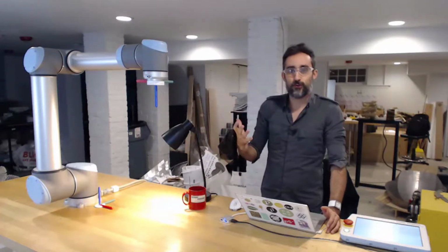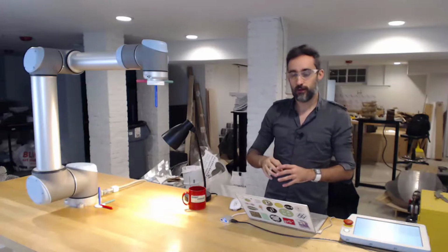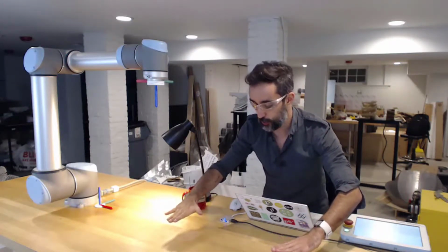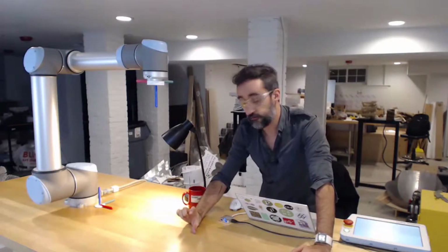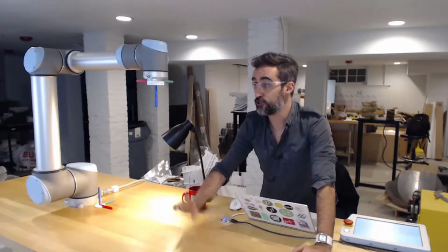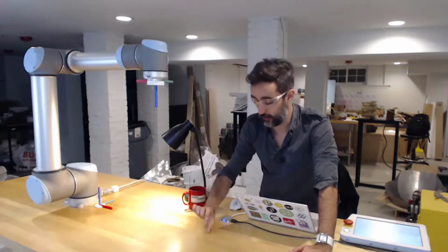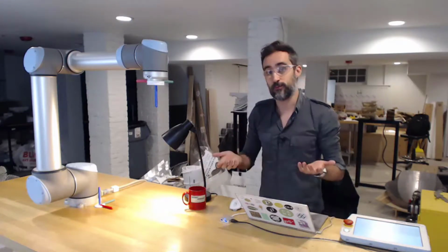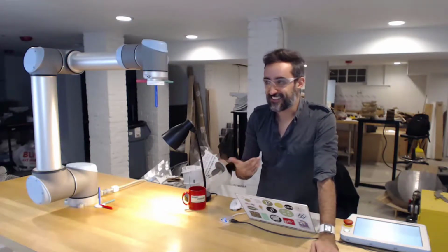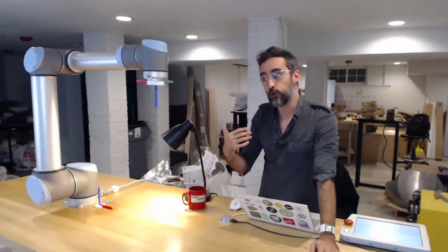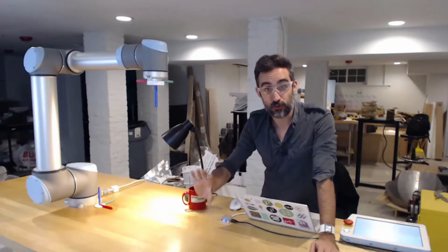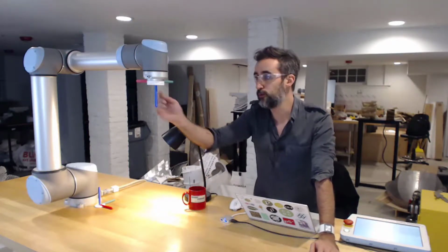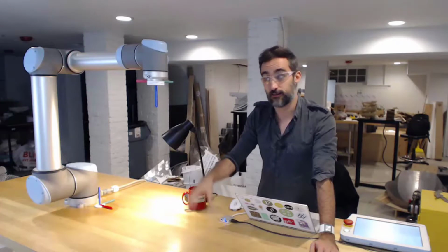So there are two things I could do. I could just write my program, and if the surface that I want to deposit glue on is at 50 millimeters from the ground, then I can just offset all the coordinates of the motion an extra 100 millimeters on top of the surface, and that's how I can work in my program. But that's not clean, that's not nice, we may forget about that offset, and also, that's only going to work for very simple Cartesian motion. If we rotate, then the rotation will always be based on the center of the flange, right?